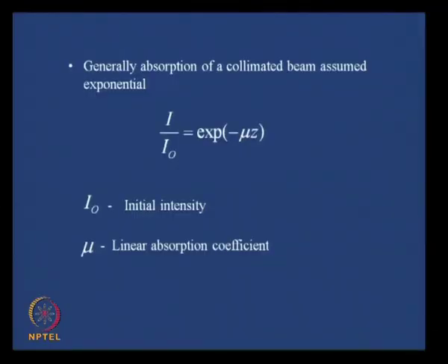What value it will have will not only depend upon the proportion of gas and liquid, it will also depend upon the distribution of the gas and liquid to some extent. But usually, whatever the attenuating process, the absorption of a beam is assumed to be exponential.